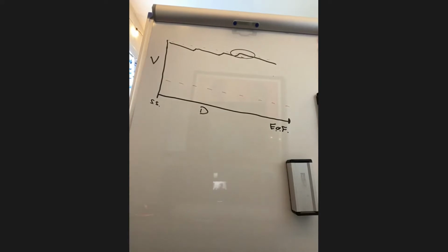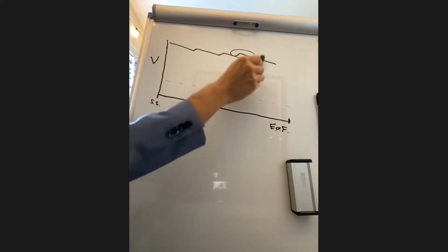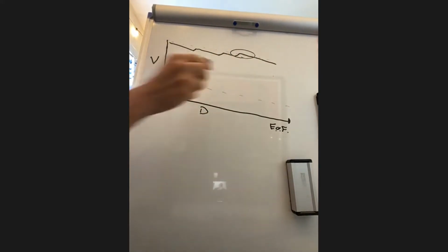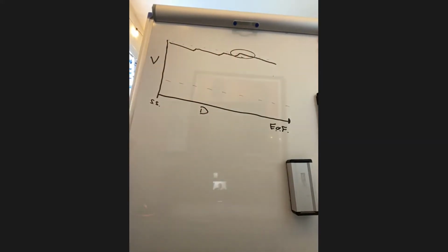So in the absence of standards like IEEE 1547-2018, utilities have been extremely conservative in the amount of solar that they can allow to interconnect to their grid, because if they hit a voltage violation like that, it's the utility's responsibility to ensure that voltage violations don't occur.